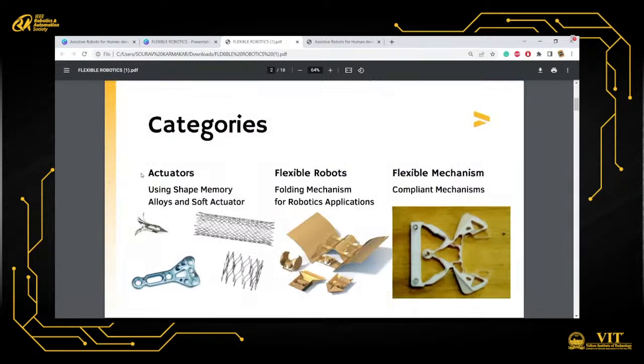So I mentioned this shape memory alloy soft actuators, and you can see this is the way they make it. There is a robot, if I'm not wrong, by MIT. They made this kind of net system with robotic actuator, robotic muscle kind of stuff, and they use the shape memory alloy. I think these are 0.25 mm diameter each, and they arrange them in such a way that it gives you the earthworm movement, and they use some fabrics too. It's really beautiful. You can just check it.